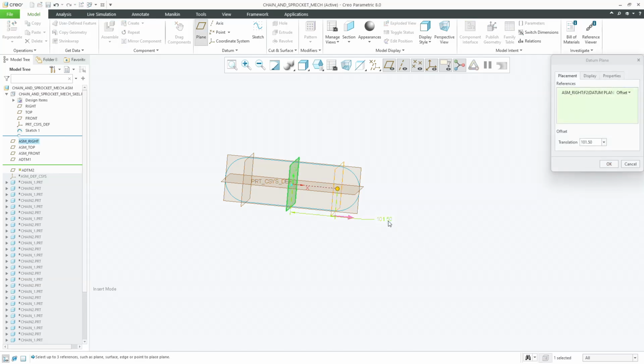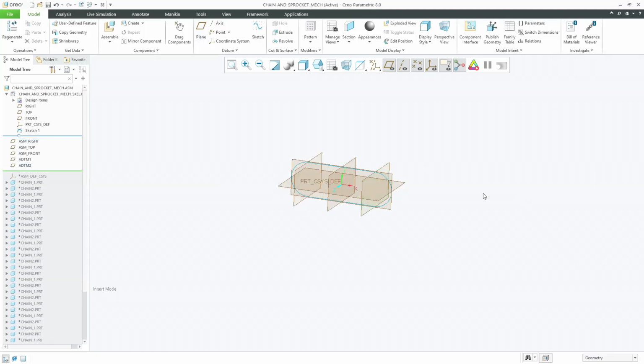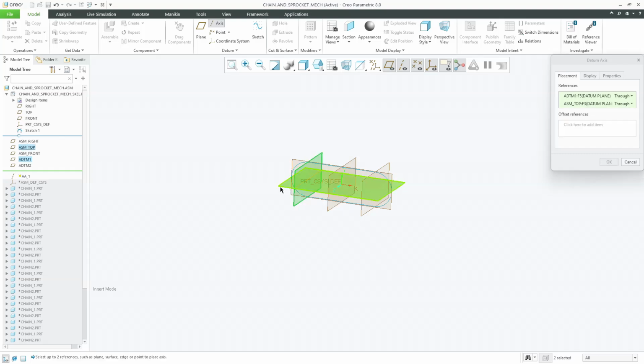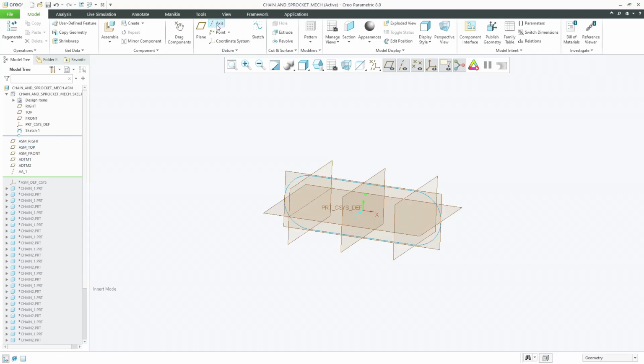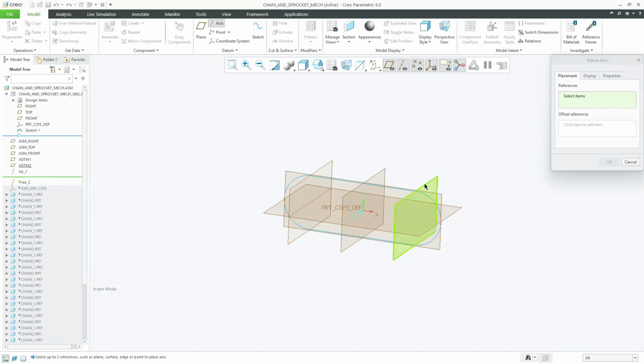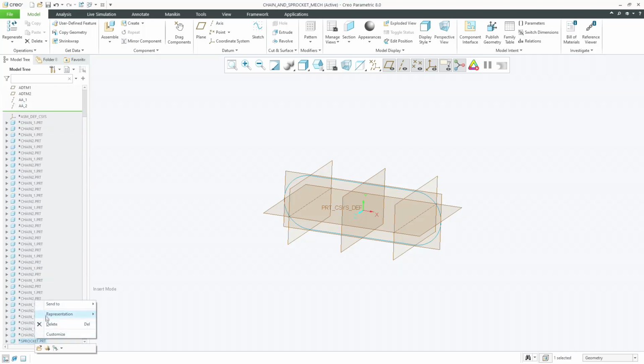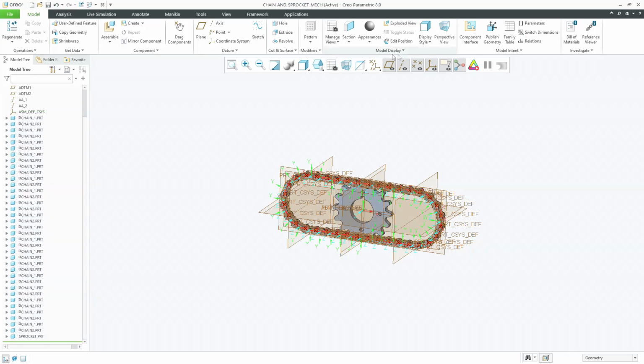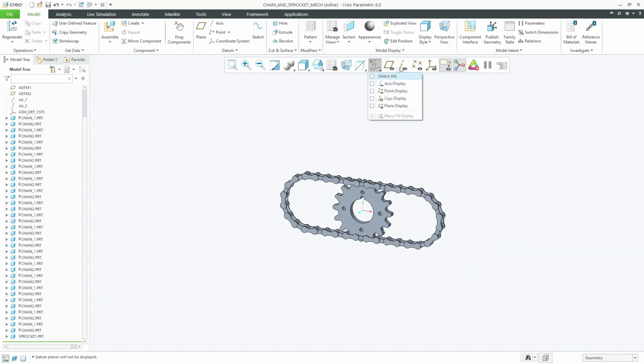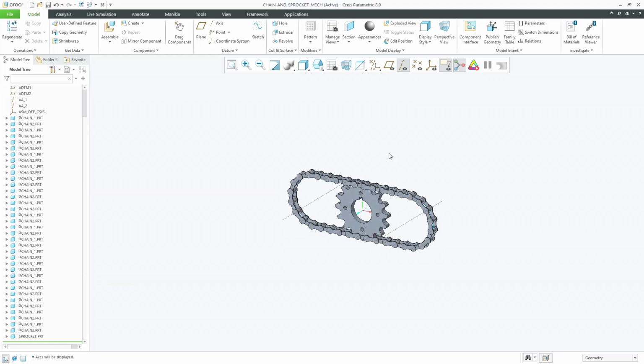So now we are going to have an axis to have a pin connection in this way for the side plane and the top plane, so that we'll get an axis towards the front direction. So I'm going to have two different axes where we are going to place two different sprockets. Let me activate all those parts, and here I'm going to enable only the axis.